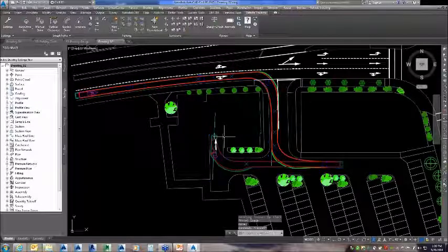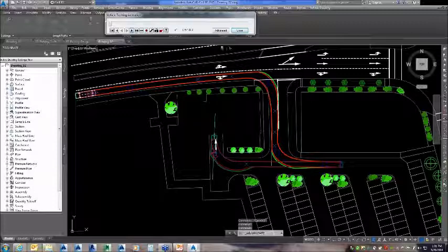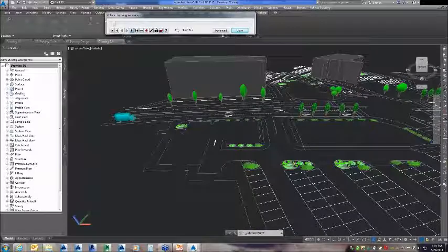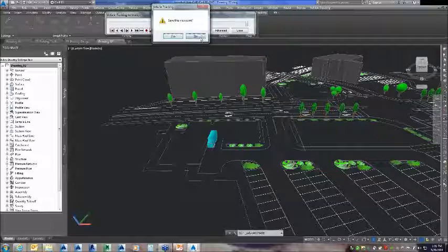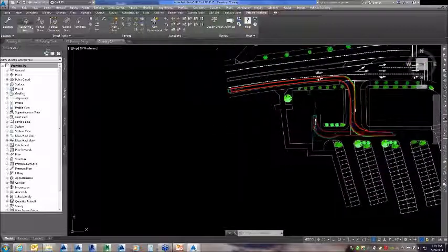It also gives me the ability to drive based upon a bearing if I wanted to. So I'll go ahead and animate, just so we can quickly look at that. We'll look at it in 3D, and I'll speed it up a little bit, just so we can see that drive through. Pretty straightforward. So just a few picks and a click, we can analyze that swept width and arc. Okay. So again, it works the same with any vehicle that I utilize.